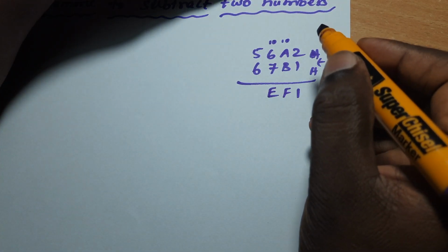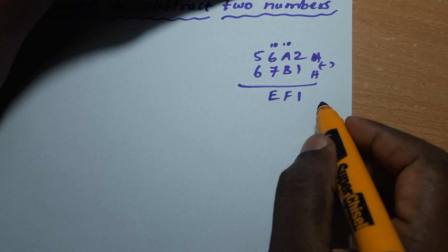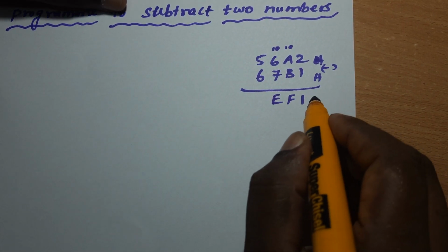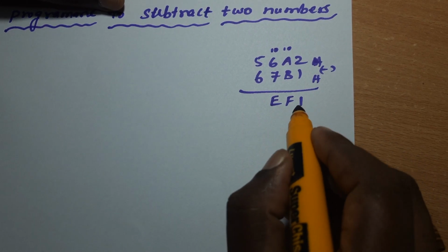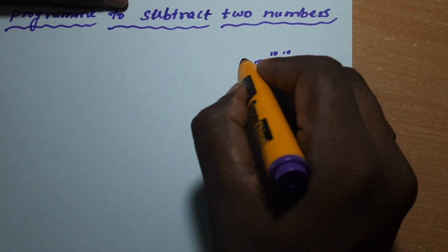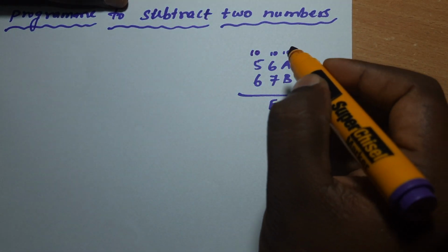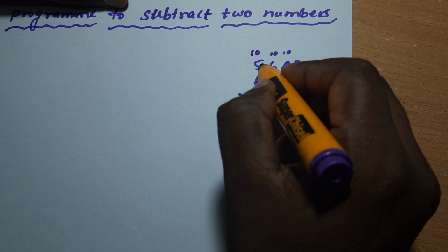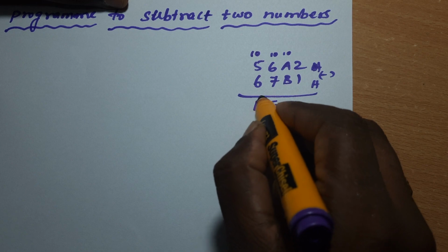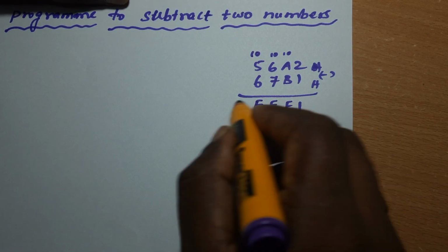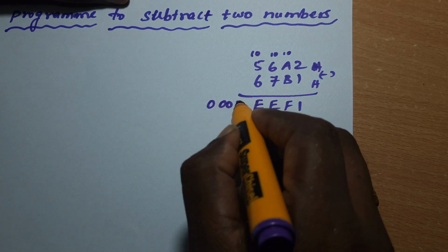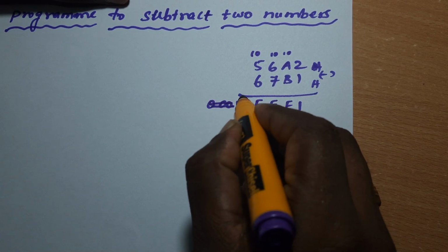Now, if you are using a microprocessor trainer kit or any assembler to do this assembly language programming, this will be subtracted by the processor. It will borrow one, and that becomes 16 now. So 16 plus 4 is 20. 20 minus 6 is again 14. This would be the answer, but this borrow is indicated as a carry.